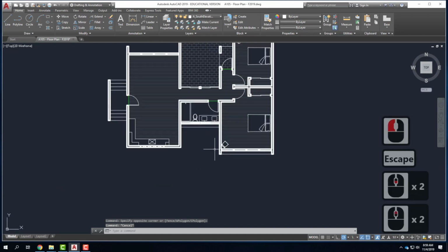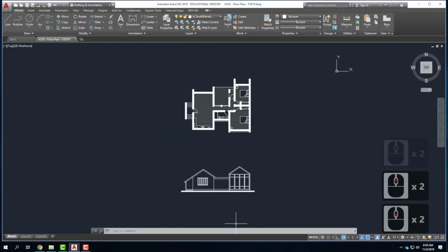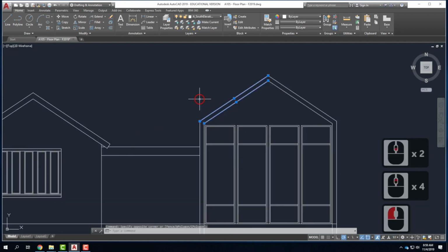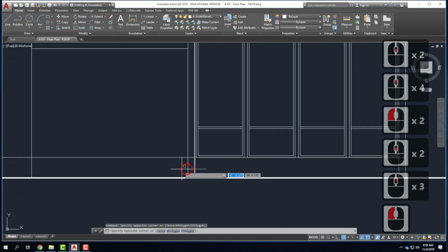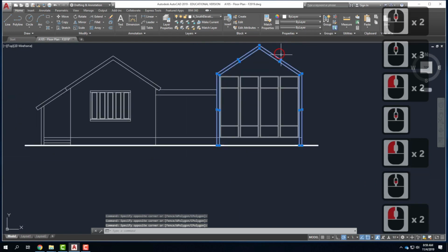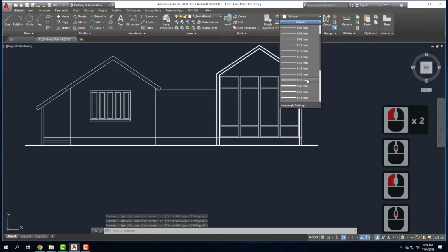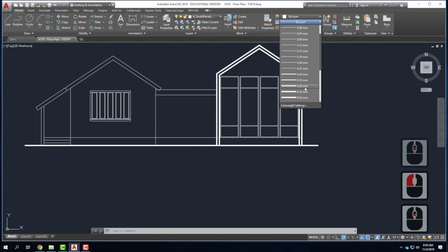Now as I look at my building, this is closest to me with these little wing walls. So I'm going to take my wing walls, there, those two, and those two, and I'm going to make them the next thickest as I go down. So I could do them at 0.4, but it's probably a little thick, so I'm going to do those at 0.3.